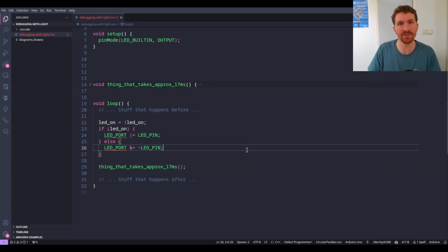It does a bunch of stuff under the hood to try and regulate the Arduino's internal timing, to try to normalize the pin definition name that you give, like pin 13, digital pin 13 or something. It needs to translate that into something else. So there is a bunch of extra work that the Arduino framework does, and that might interfere with our timing. And I want to have as little influence on the timing of the system as possible.